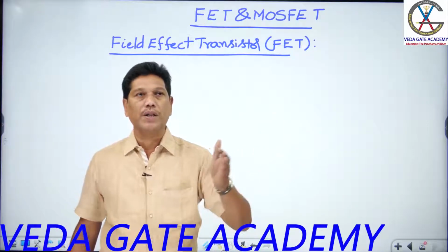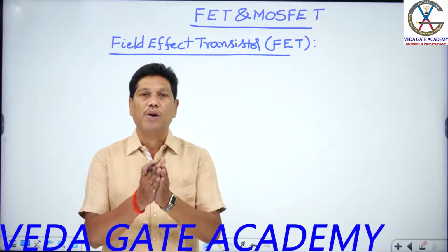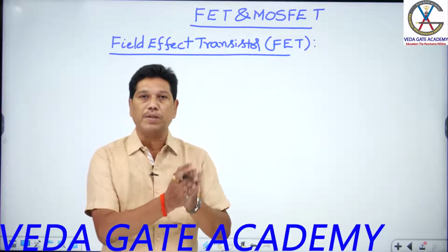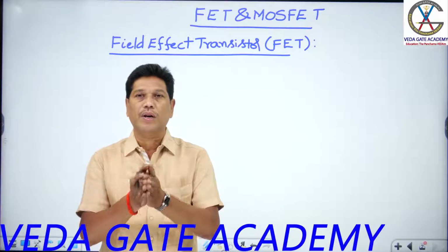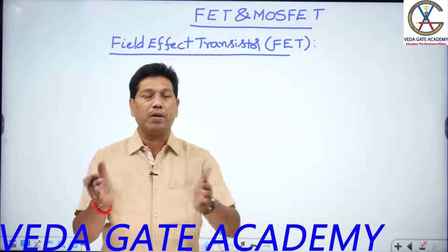So you find many advantages in FET as compared to BJT, but only one drawback is there. As compared to BJT, the gain is less, I told you. Simply you can say that the gain bandwidth product is poor. What is the gain bandwidth product, sir?